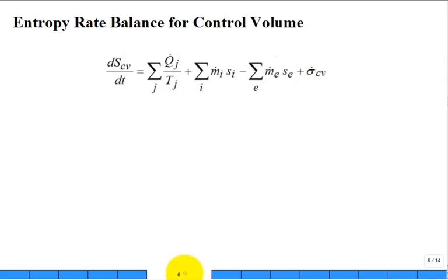Well, we move from a closed system to an open system. What's the difference? You can have mass transfer across the boundary of the system. Well, we want to write an entropy balance equation for a control volume. So we think about how the entropy inside that control volume changes with time. It can go up if you're accumulating entropy, or it can go down. If it's steady state, and 90% of your problems will be steady state, or even 99%, often that term is zero.